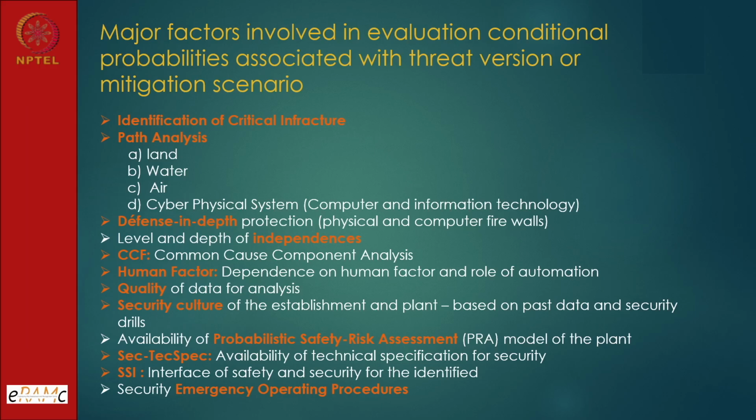Defense in depth evaluation should tell us the level of redundancy, diversity, and common cause elements which are there. What is the potential of common cause failure? What are those events which will lead to complete jeopardizing of the physical system? What are the human factors that will jeopardize my complete system?